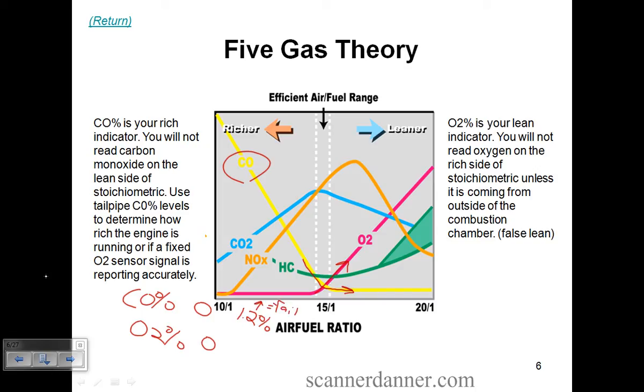And then 94, 95, right before OBD2 came, actually they didn't start doing OBD tests until like 98. So we were still doing tailpipe tests on OBD2 cars before the program came out. And they dropped that to like 0.8% or above equaled a fail on the newer car. So I'm only giving you that number for perspective of how much 10% is in my captures coming up. How much is 10% if less than 1% is a fail? I think we can all understand that's a pretty high number.